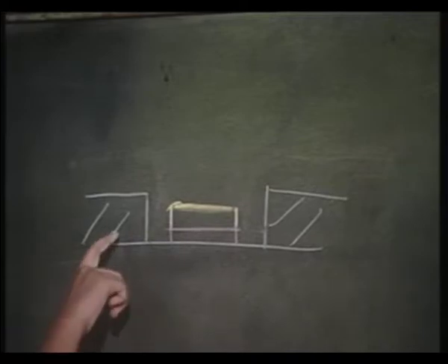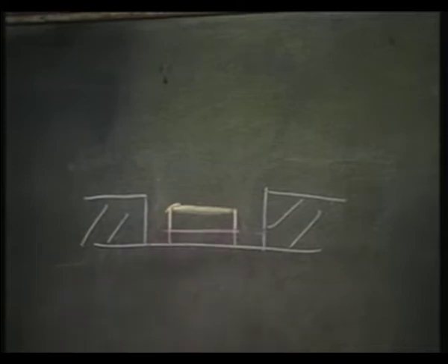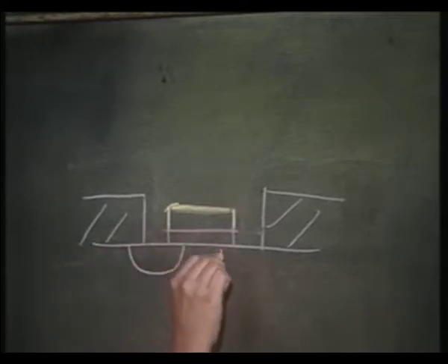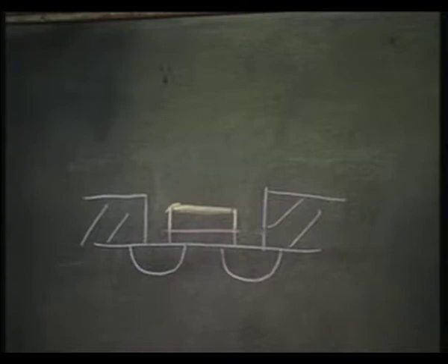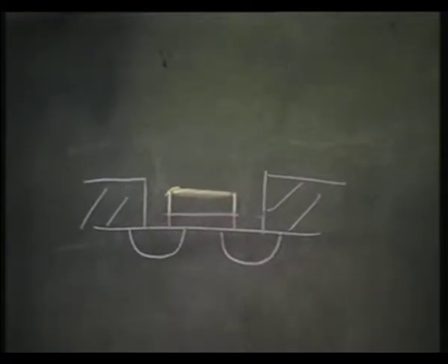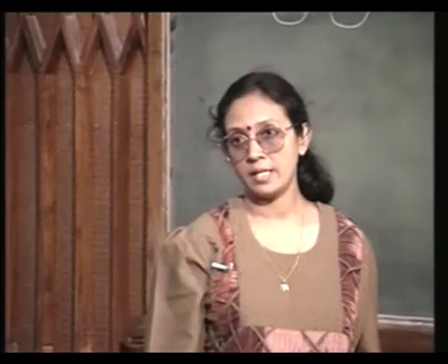So, you see you have certain regions protected by the thick field oxide and the gate region protected by the polysilicon, and now you can subject it to high temperature processing and you can have source and drain which will be automatically aligned to the channel, right. So, this is the self aligned polygate NMOS technology.